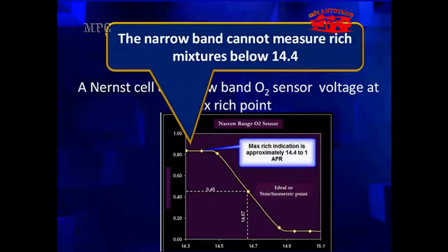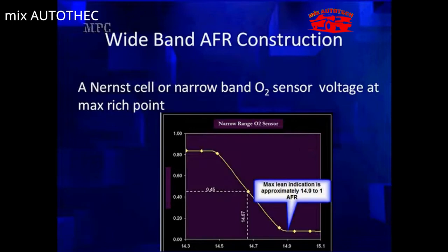Some people use this voltage to see if they're getting sufficient fuel flow. Well, the ideal or a good, reasonable number for wide open acceleration is 13.2 to 1 air-fuel ratio. There's no way for this to measure that level. So don't use this just for wide open throttle, saying I got plenty of voltage if it gets to some number. Max lean is about 14.9, and the PCM is going to take the vehicle down and say, can it get to the maximum lean?